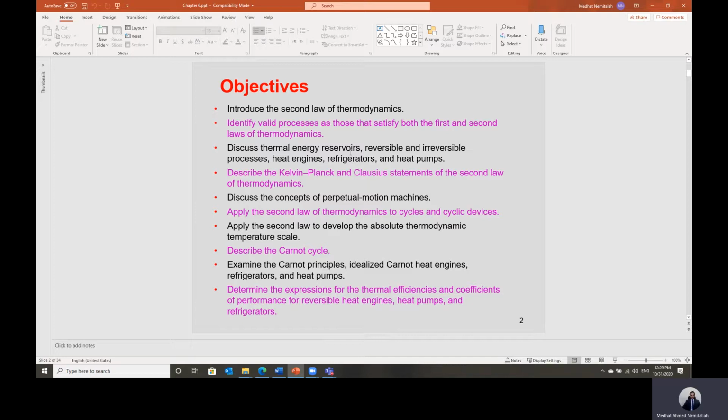In the case of a heat pump, it is the same cycle as the air conditioning system. Like the air conditioning system in your car, it can be hot or cold. Also in your house, we have the air conditioning split unit. It can work as air conditioning to cool down the air, or it can work as a heat pump, as a heater. The idea of the refrigeration, heat pump, or air conditioning cycle is that we absorb heat, either from a food compartment or from the air inside the room, and then we reject this heat in the condenser through the air conditioning unit.